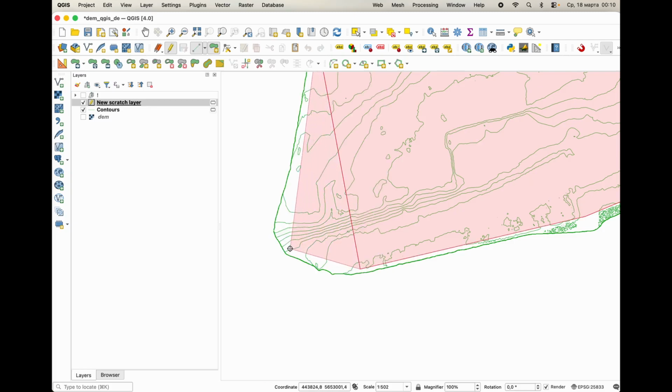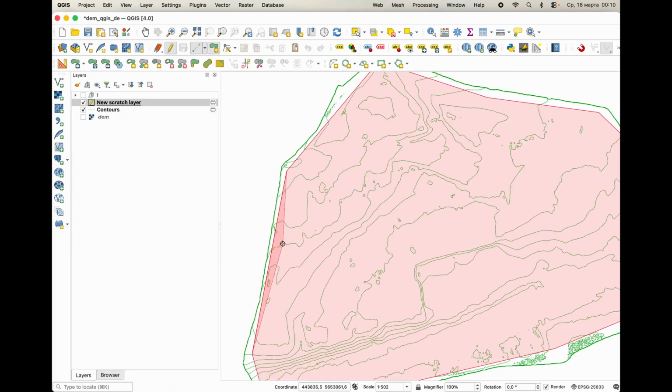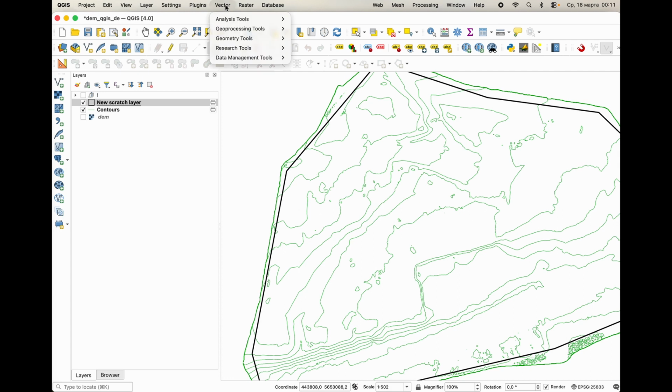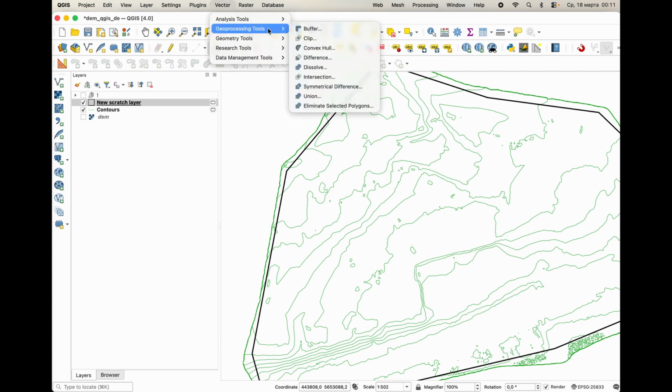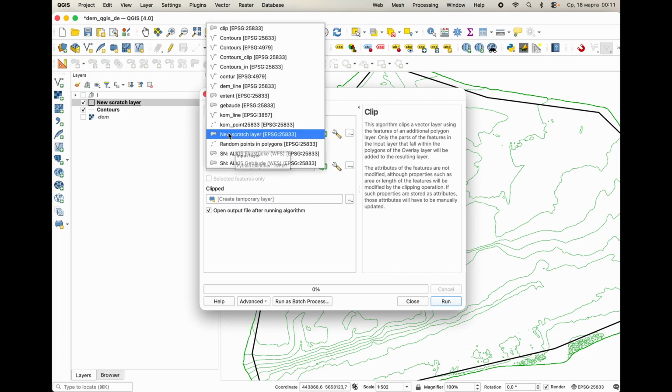As always, one important point here is the coordinate system. We need to really make sure that all layers use the same spatial reference system, and the contour lines, the clipping boundary, and any additional reference layers must match correctly. Otherwise, the geometry will not align as expected. So we check the coordinate system, make sure everything is consistent, and then continue.